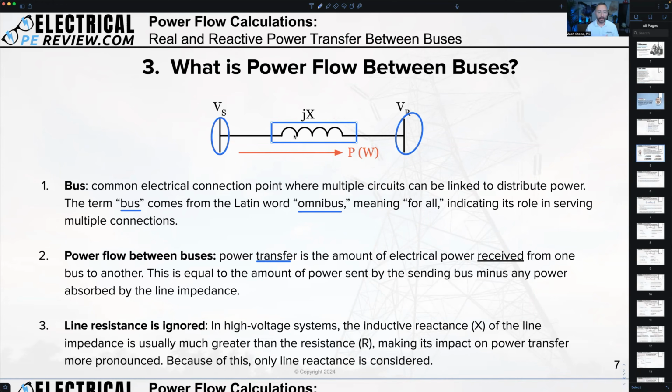How is this helpful to us? It can help us spot mistakes. It can help us know when something doesn't quite look right. It'll help us model systems better. And the other benefit in the real world is that it's an easy way to determine, if you've got complex voltage measurements, say from your relays between two buses that are connected together, you can know right away, pretty much off the top of your head: is there any real power flowing?